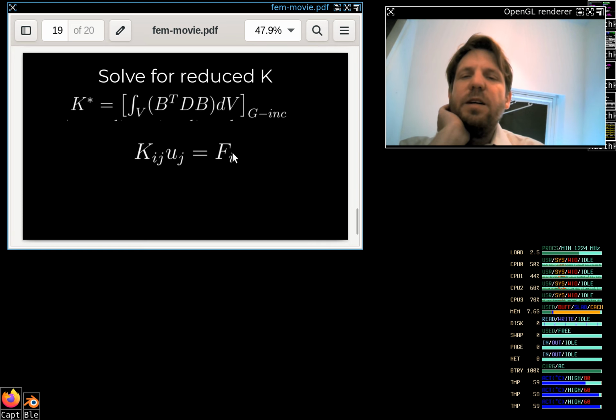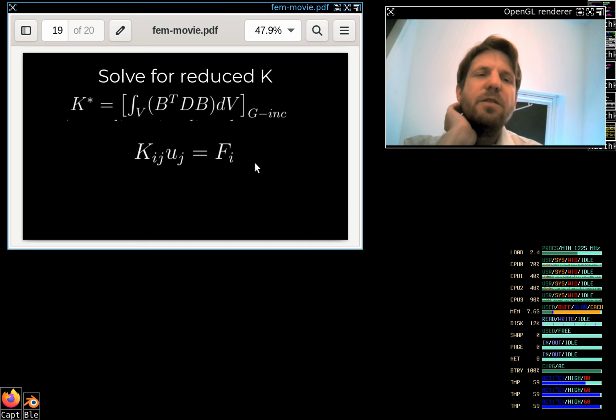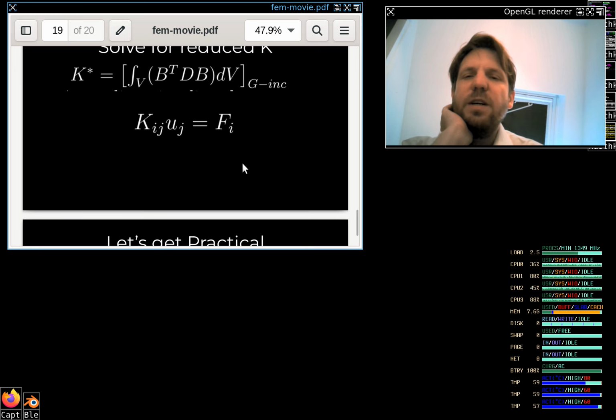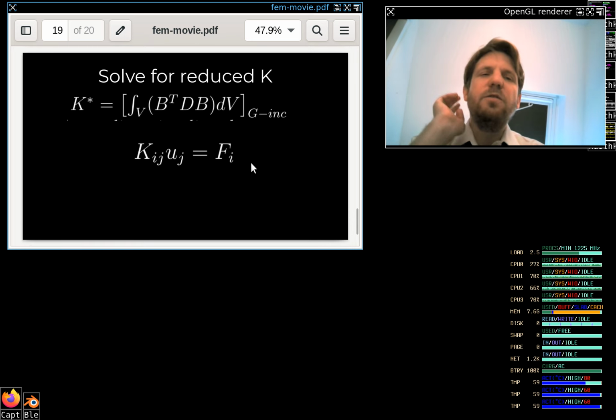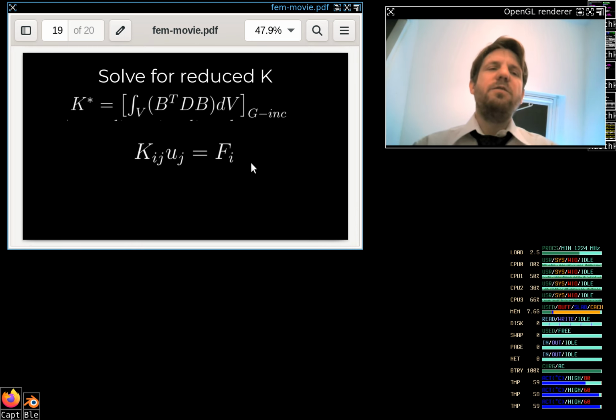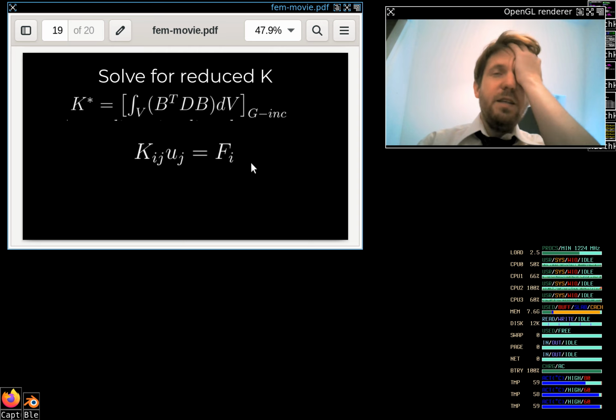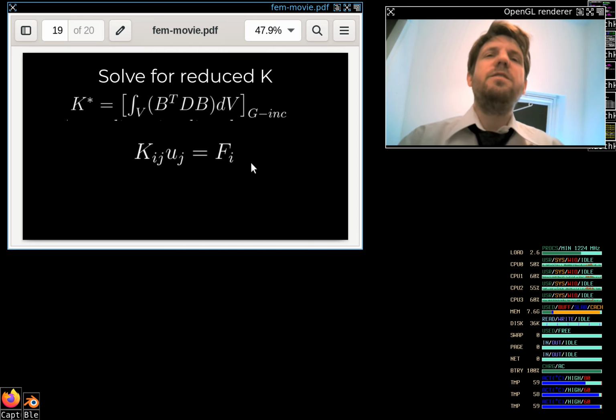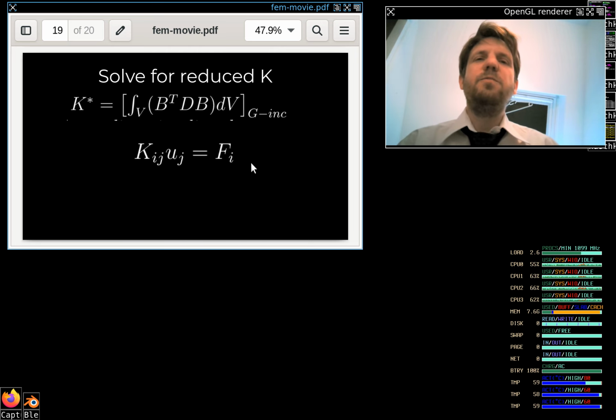That's the way it is. Yeah, that's the way it works. So you don't have a graphical interface to this. You just have an input file, and I will show you how to do this practically and how all this looks like. But this is a basic finite element solver. Basically, you can build a virtual bridge out of these little hexahedrons, and imagine forces, put forces up there as if a truck goes over the bridge, and see how the bridge deforms. Things like that. You can do it with them.